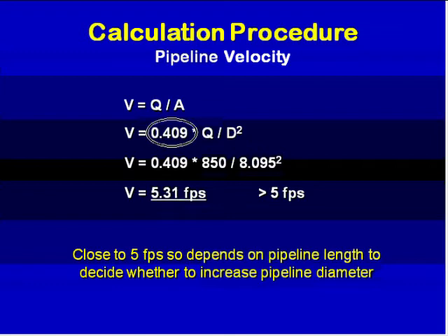So that might be a pressure relief valve. It may also be a situation where we allow air to exit the pipeline in the form of an air relief valve. The pipeline going to the center pivot, with sprinklers that allow water to exit along the pipeline of the center pivot, would be helpful in this regard. So basically a way for some of that excess energy to exit the pipeline itself.